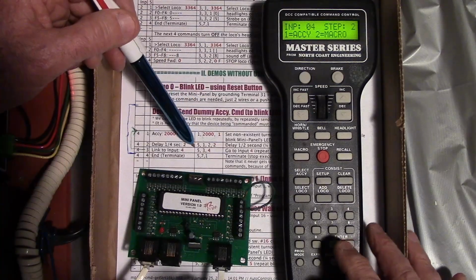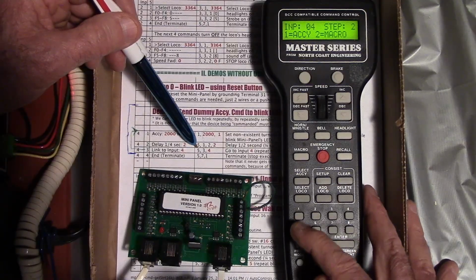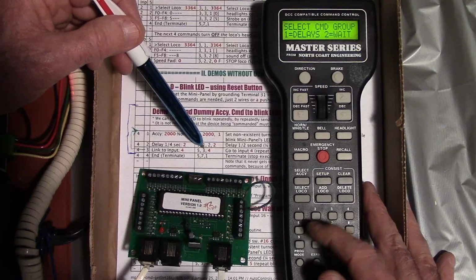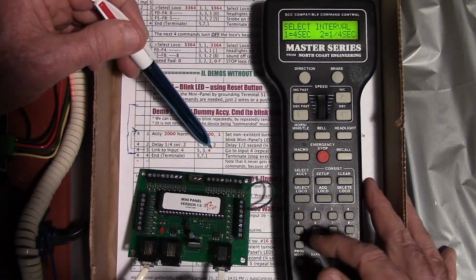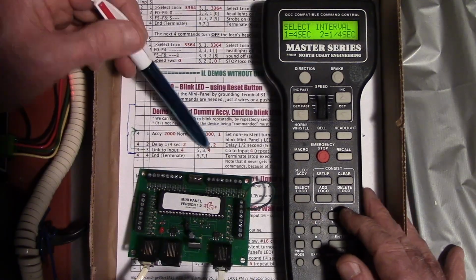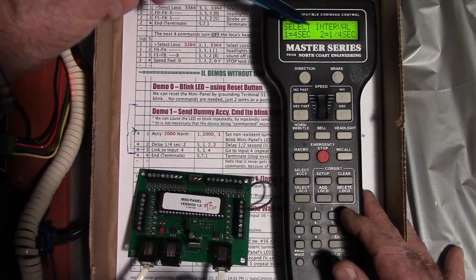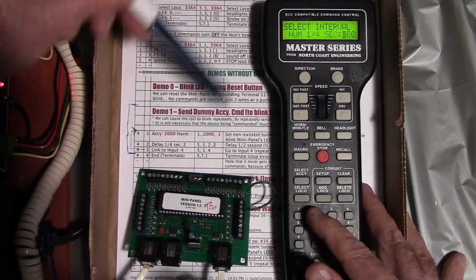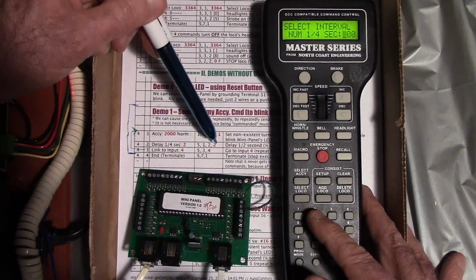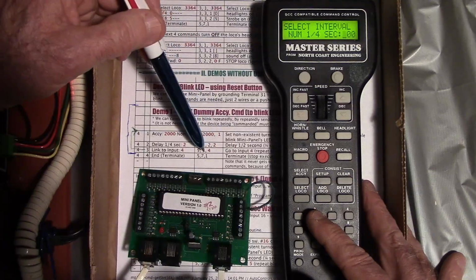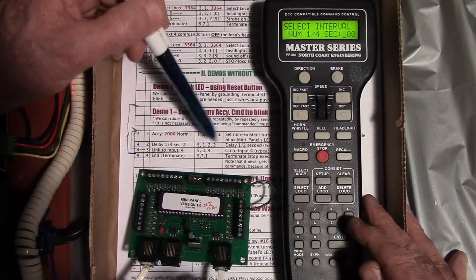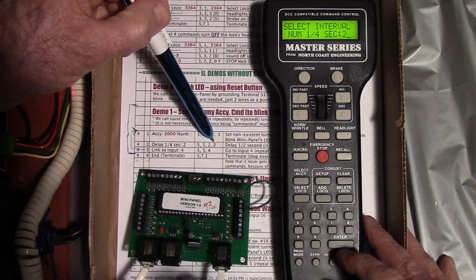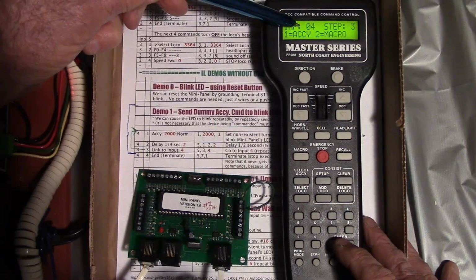Now we're ready for input 4, step 2. So we're going to push a 5 for other, 1 for delay, and then a 2 to indicate quarter-second delay. There's also 4-second delays. I usually use the quarter. So the number of quarter-second delays, that's the number in red, 2. Enter that. That gives us our half-second delay.